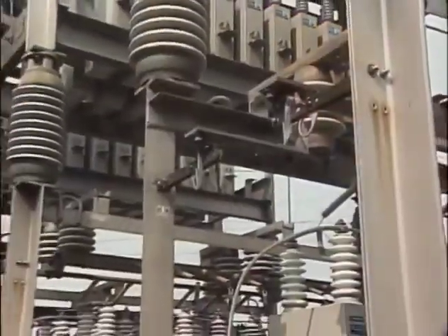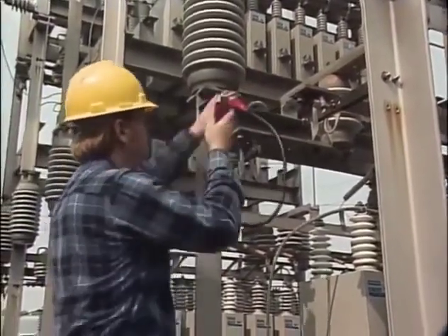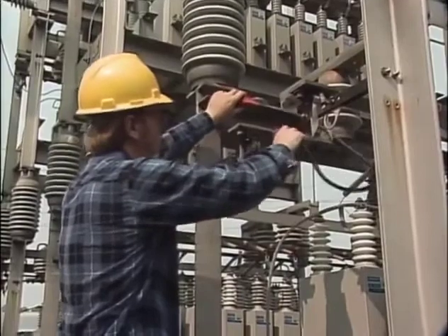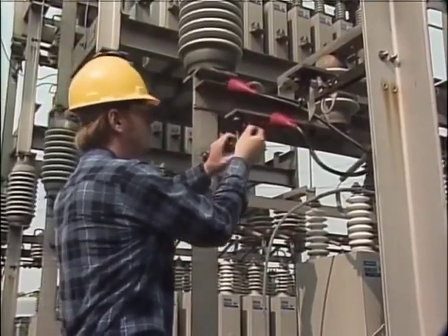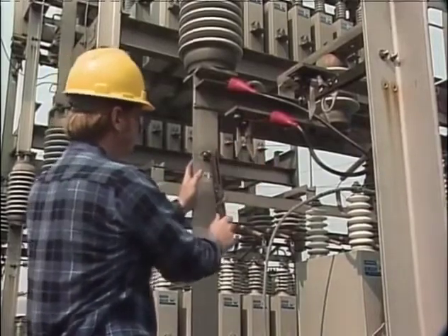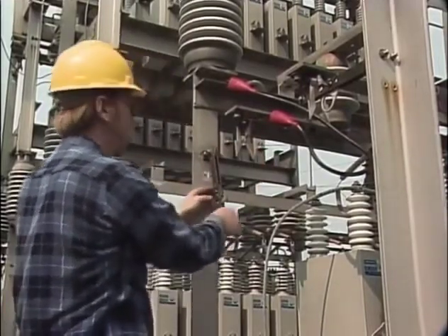If the capacitor bank is equipped with shorting and grounding switches, each switch should be checked. A precaution is needed here. Before doing any work on a switch, connect jumpers across its connection points to ensure that the bank remains grounded while the switch is being serviced.